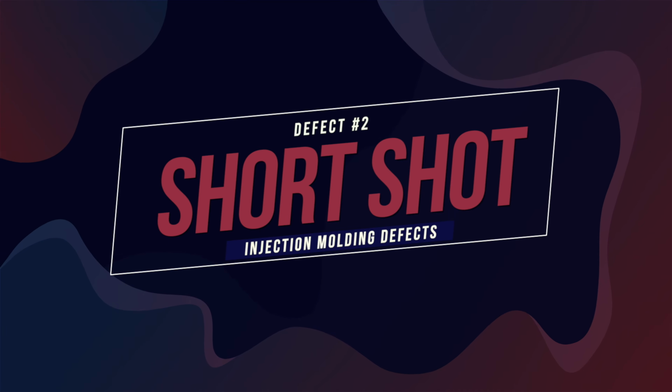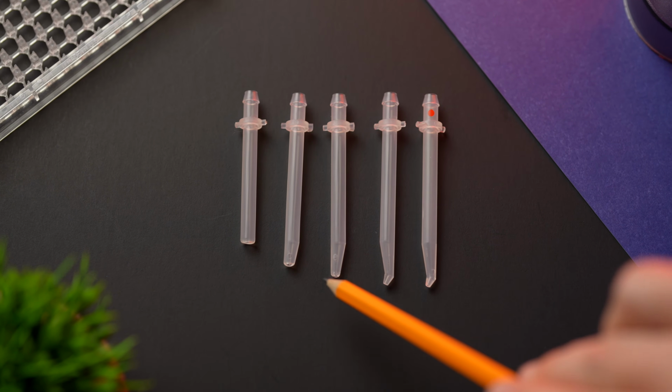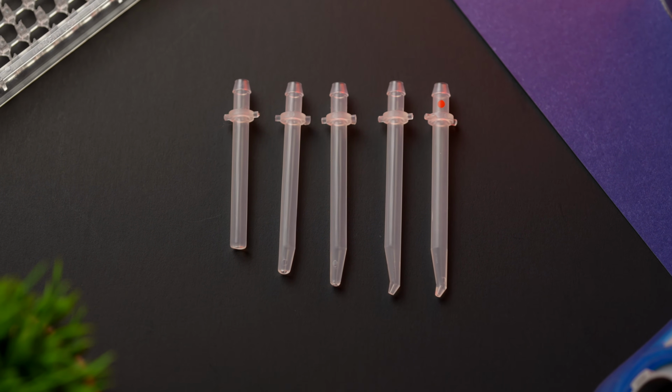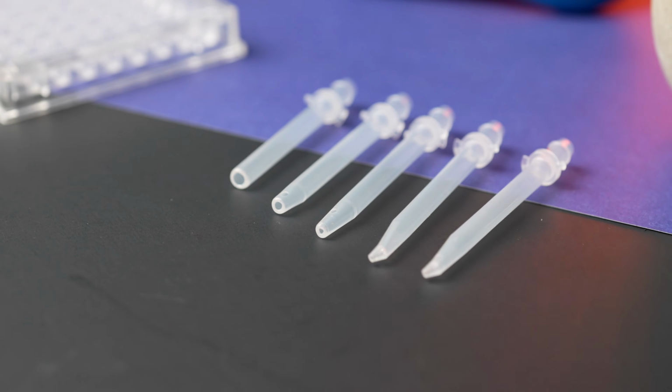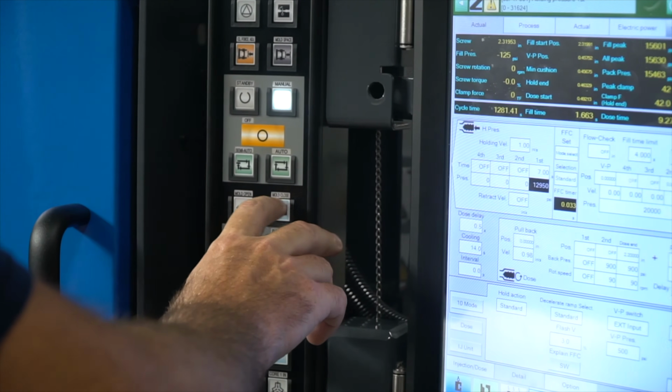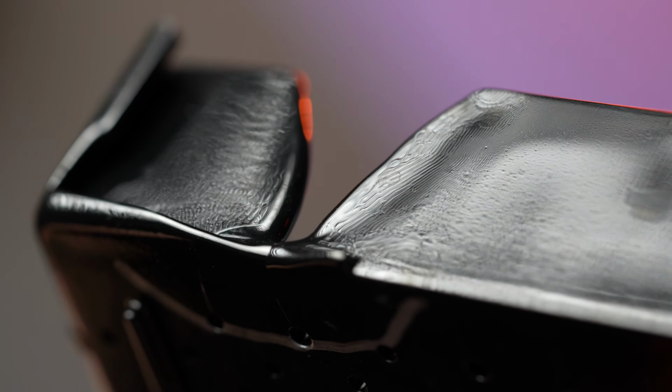The next injection molding defect is called a short shot, and this simply refers to an incomplete part where the melted plastic is not fully filling the mold cavity. As you can see here, short shots can range from entire sections of the part not being filled to very subtle defects that need to be carefully looked for. In smaller parts, short shots are often the result of a material with a high viscosity, meaning it does not flow easily, especially into hard-to-reach areas. In this case, you may want to consider increasing the melt temperature or mold temperature to allow the material to flow more easily, or try an entirely different resin with a lower viscosity.